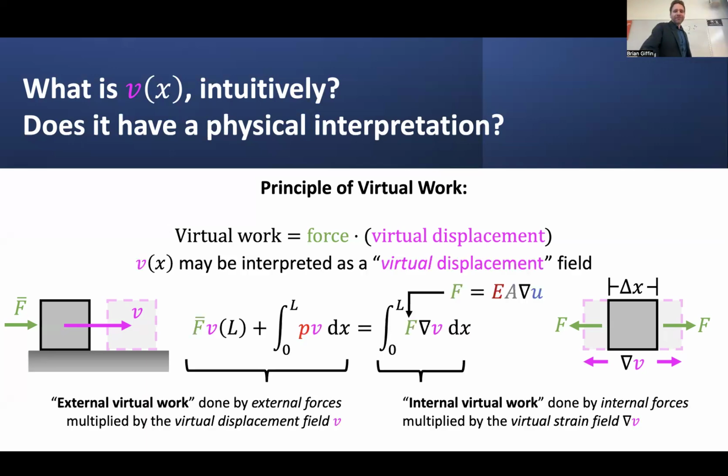Now, the principle of virtual work effectively establishes this balance: whatever external virtual work would be done on this system, moving through this particular virtual displacement field, must be balanced by any internal virtual work that would be done in moving through this internal set of forces stretched through this virtual strain field. So, in effect, this is a statement of balance between external virtual work and internal virtual work for any possible choice of